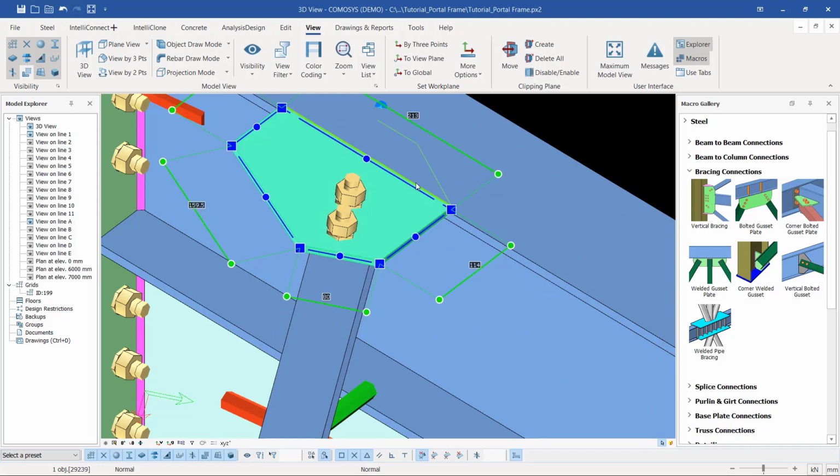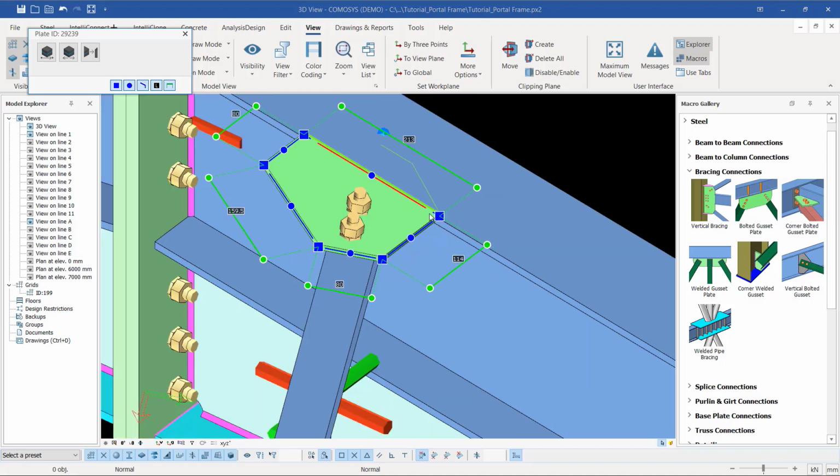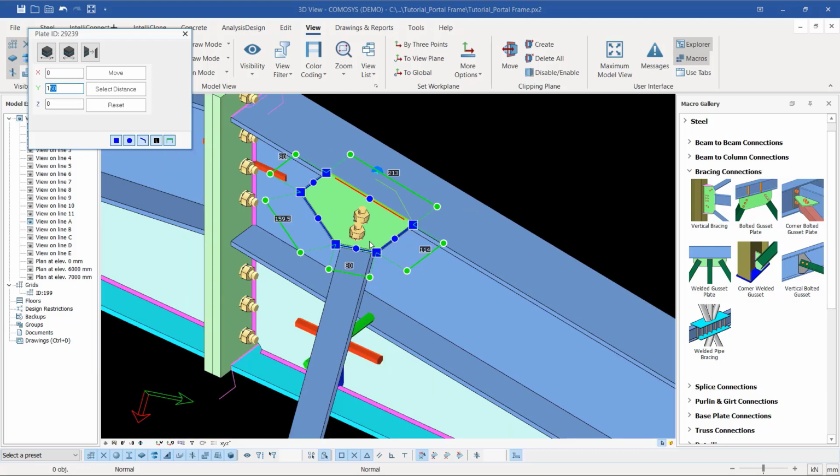Select on this member. I'll select on that. I want to adjust this member to touch the far end of the flange. So I'll come here and select on that. So this from here to here is 150. So this 150 will just feed on the x-axis. First of all, make sure everything is in the same orientation while doing this kind of modifications.